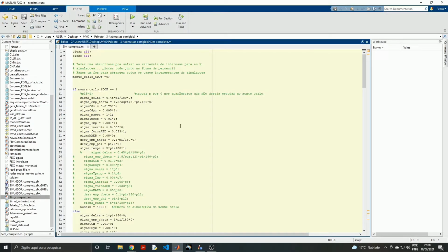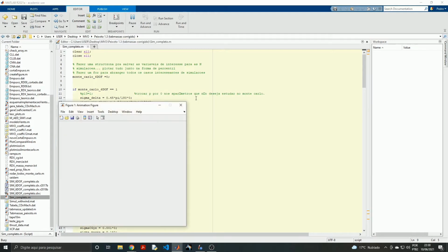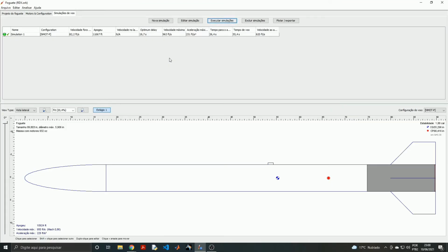In the later stages of our project, we have access to further aerodynamical data, such as the aerodynamic moment coefficients and the full mass distribution of the rocket. This enables us to perform a 6-degree of freedom analysis on our flight, providing much greater accuracy than the previous simulation. In order to validate the data we gathered from our own student-made simulators, we utilized the OpenRocket software. This is a commercially available simulator designed specifically for rocket modeling. Furthermore, all of the data shown in our report actually comes from this software.